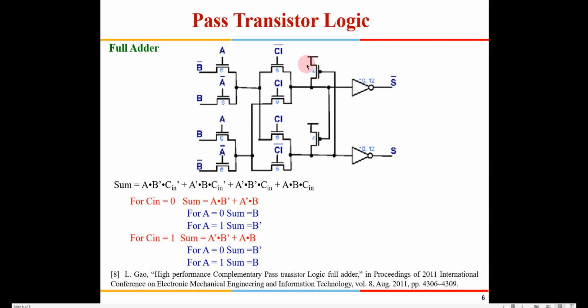Okay, so like we learnt in the dynamic circuit in the last class about a keeper transistor, you can call this a keeper transistor here also. Similarly, this is generating a sum bar here. Once it is generating a sum bar here, this is a keeper circuit, so you are feeding it from the sum input.